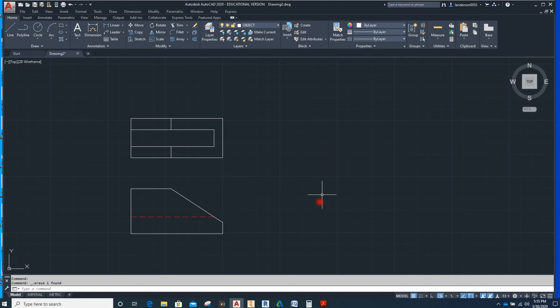Boom. So you're like, how do we draw this? Now see, these are the way they should be. Your front view is going to be right here. Your top view is directly over top of it. Okay? Just imagine this is a big paper box. And this is your top view. It's your front view. Now we're going to draw your side view looking at this angle here. So we take a line and we go up here. If you hit your tab button, you can hit your angle listing and make it 45. Okay, and there's that.